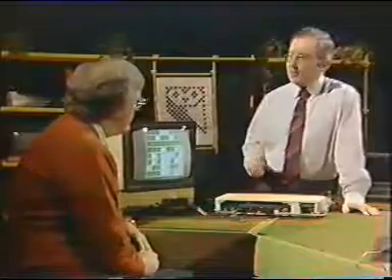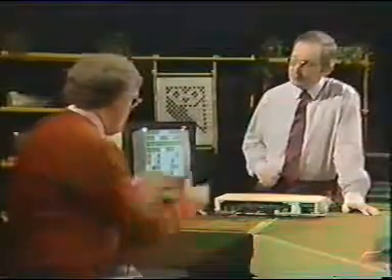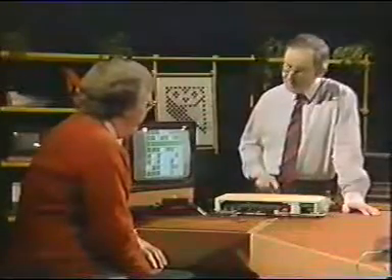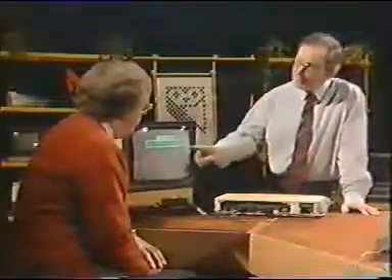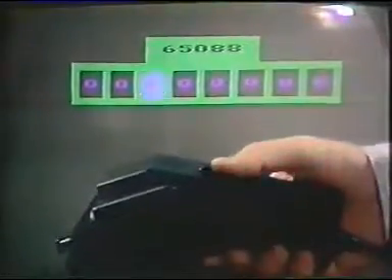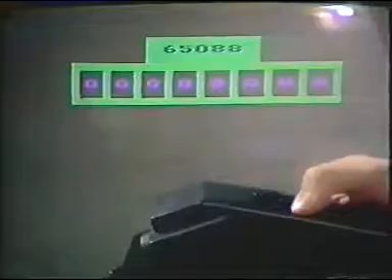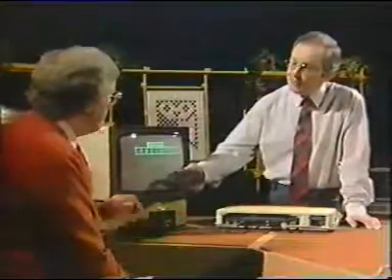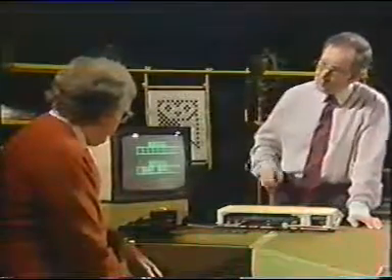Remember that we had a memory map, a 64K memory map, and we used this display to illustrate. Right, each one of these is a byte running across with 8 bits, and there's about 65,000 in the machine itself. Well, what happens inside the computer? We've got a couple of those addresses set aside, not for RAM, random access memory, but for input and output devices. And here's one particular address, 65,088, which is an input connection. When I push this button here, the bit changes, and if you push the button on your games paddle, a different bit changes. So the input from this is being fed into this address, and we can sense it there. And the output is at another address.